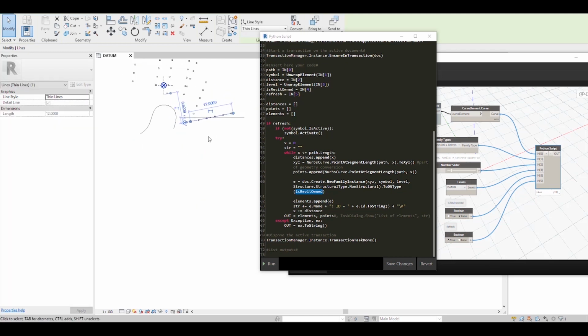So it is very important to understand when we want to swap this between the two owners, which might be Dynamo, might be Revit. And this is basically done by this method when we start to create. It's kind of wrapping again the object and sending it back to Revit using this one, whereas the unwrap is unwrapping the element from Revit to be used in Dynamo. So it's kind of wrap or unwrap. It's just called in a different way. But I like to think about it this way. This is exactly the vice versa of unwrapping elements. And so using these two, you can quickly